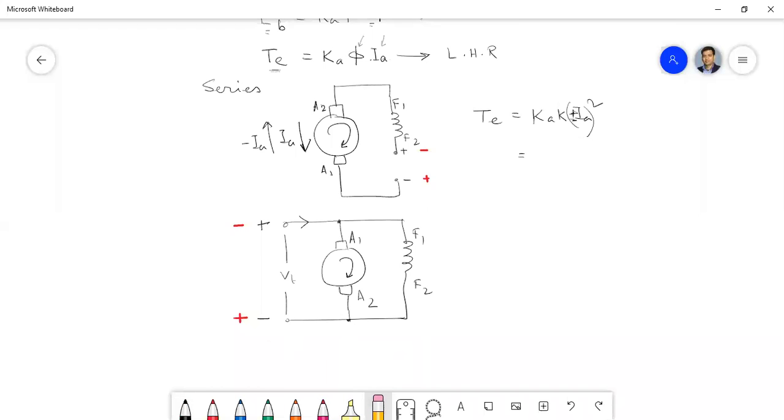Don't assume anything. Sir, it will stop. No, I have stopped it, then I have changed the polarity. Sir, then it will rotate first at very low speed, and then it will stop rotating because cumulatively the flux will decrease. You haven't got my question.